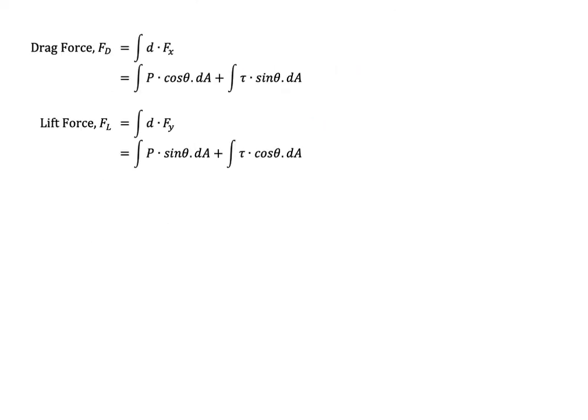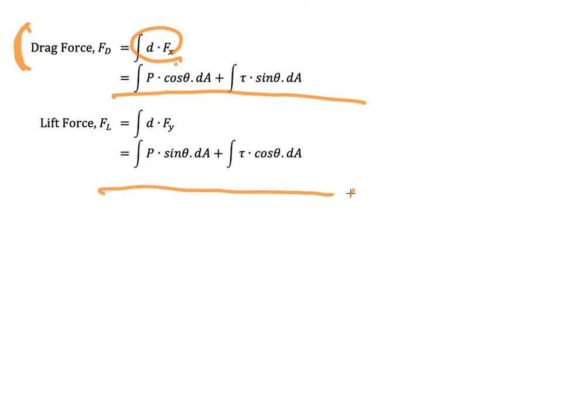So if we do the calculation, we try to construct the equation for drag force. We could say that the summation of x direction forces becomes like this: P cos theta dA and tau sin theta dA. And these are the terms for the lift force: P sin theta dA and tau cos theta dA.